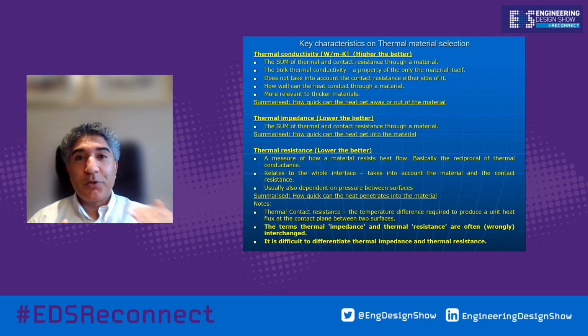or your system to the interface. So you want to make sure the interface does its work in terms of dissipating the heat and moving the heat away, but you need the thermal interface material to move that heat from that hotspot to the interface. So it's a given, you want a high value. Okay, the next two characteristics.